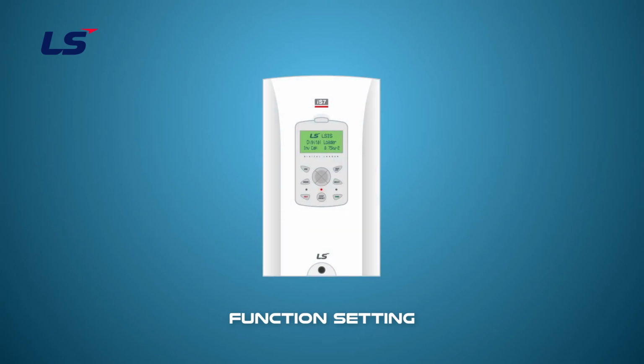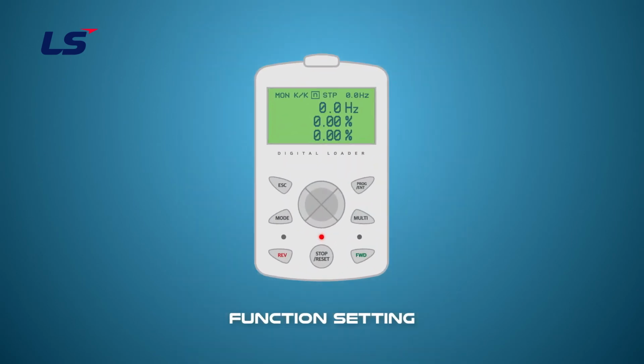Now, let's use the keypad to set the parameters related to pre-PID. First, press the mode key on the initial screen to move to PAR mode, and then press the right arrow key to move to the APP mode. Then, move to APP Group 34 and set the pre-PID operation frequency. In this example, we will set it to 30 Hz.